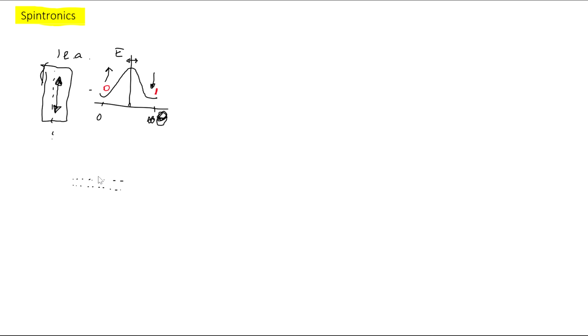And at the same time, if you put them too close to each other, so if you have one nanomagnet and the other nanomagnet too close, then if you magnetize this one this way, it would produce a magnetic field that would influence the other one, and they would be locked together. So they should be spaced out so that the field originating from this magnet is weak enough not to influence the other state. So the energy produced by the field should be below the energy barrier of the neighboring area.